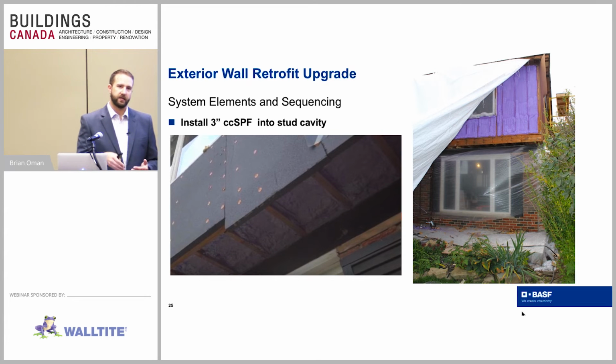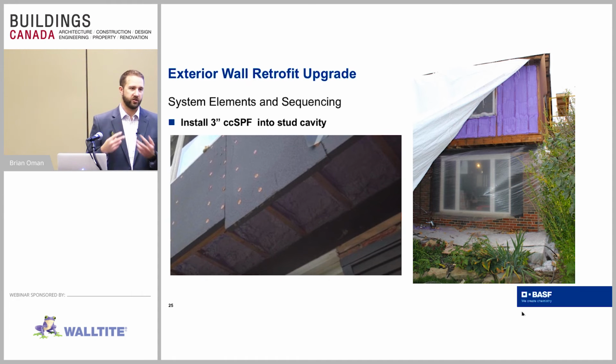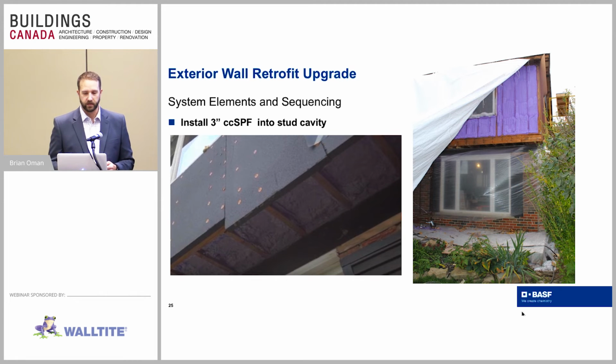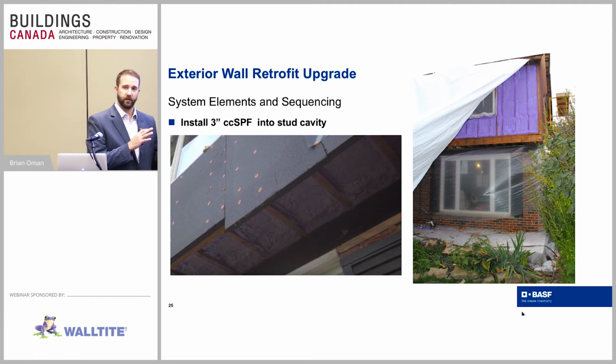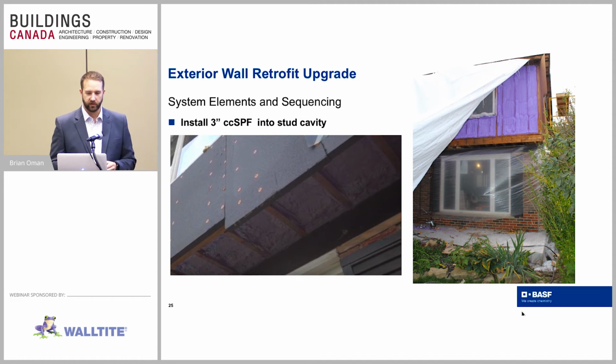We're sealing directly to that, so now we're not getting any infiltration of air or moisture in or out of our floor cavity space. And that's going to be the biggest problem in these rim spaces, is that air leakage, that air movement, and the moisture that's associated with that air movement is going to deteriorate these spaces. So not only are we improving the overall efficiency and comfort level, but we are also improving the durability of the structure at the same time.